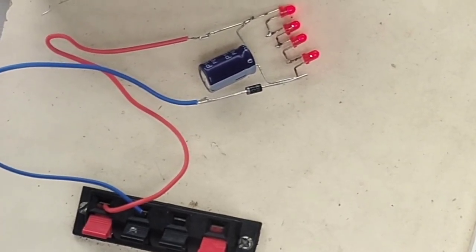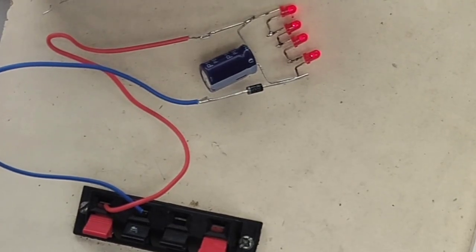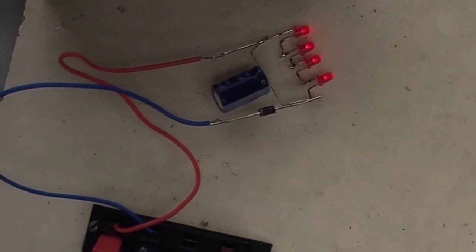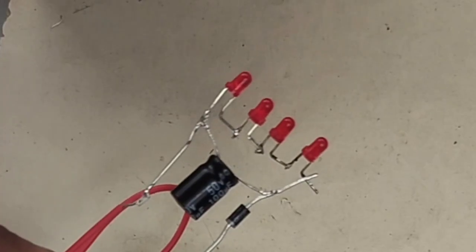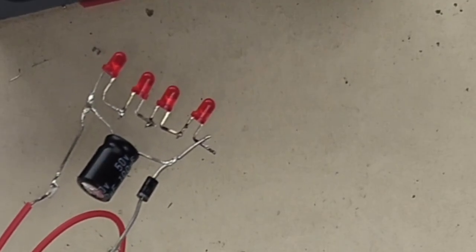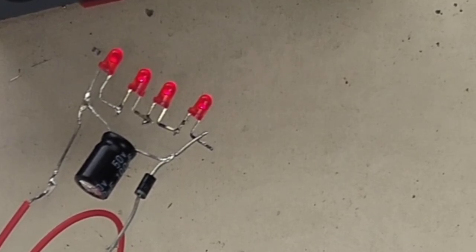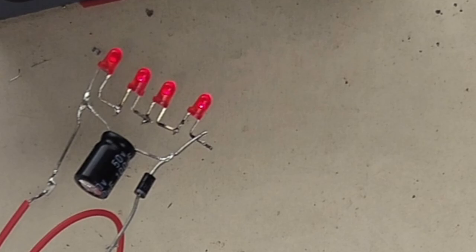You can see I'm getting continuous on LEDs, and that is because our capacitor gets fully charged and will give the complete current in the negative half cycle. Here I have changed the value of the capacitor to 100 microfarad, and here you can see the blinking LED I'm getting, right? So this is why the capacitor value matters in the circuit. It acts as a battery itself.